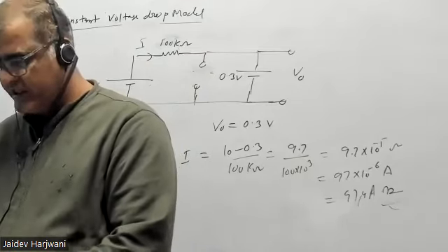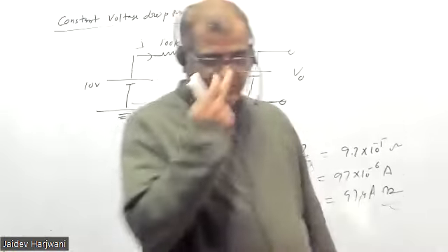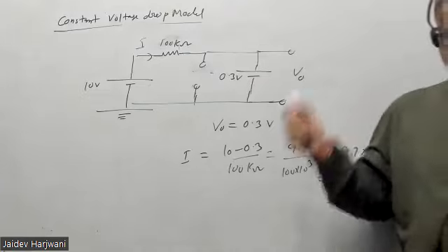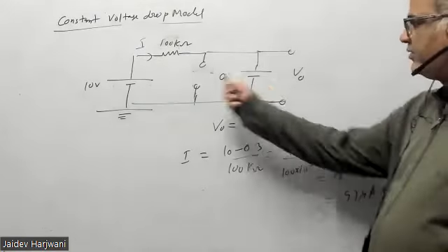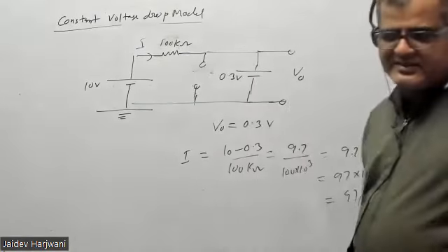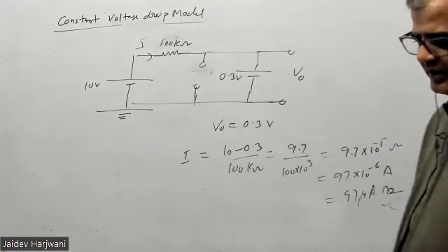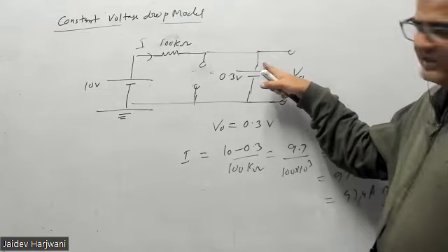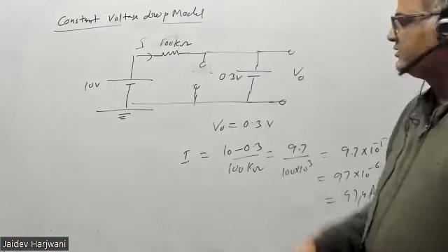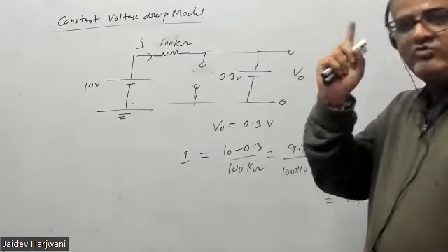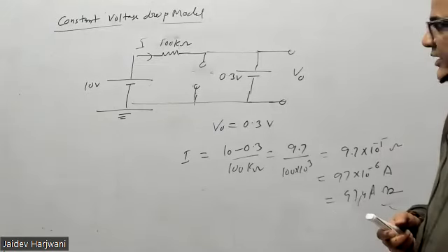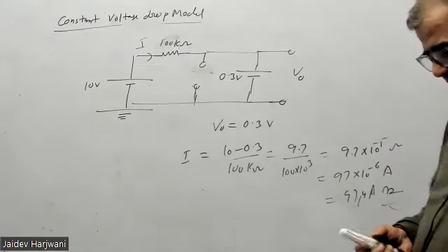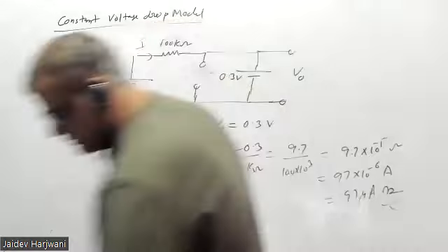Is this point clear to everyone, what I said now? Yes sir. If there are two parallel branches of diodes, maybe with one resistor also there, the branch where you require less voltage will turn on first. Okay, keep that in mind.